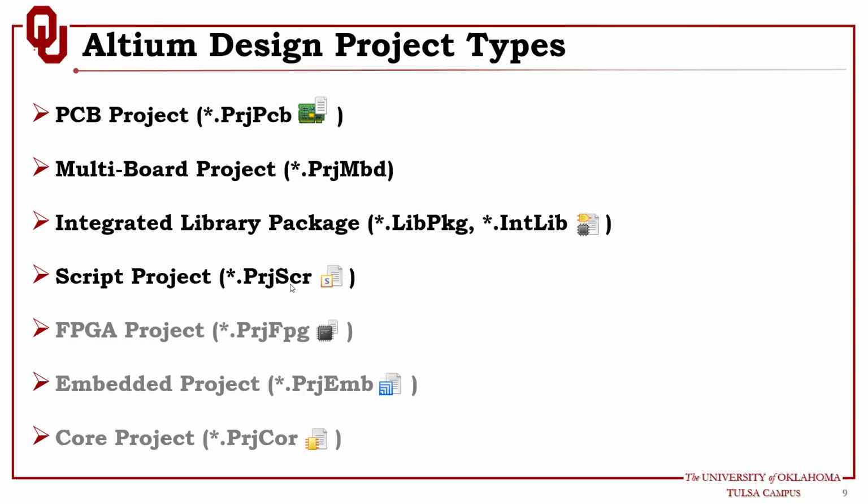You can write the script within Altium Designer, and there are 2 types of scripts: script units and script forms. A script unit can use the application programming interface, API, to modify design objects on the design document. Script form hosts controls as well as using the API to provide script dialogs that act on the design document